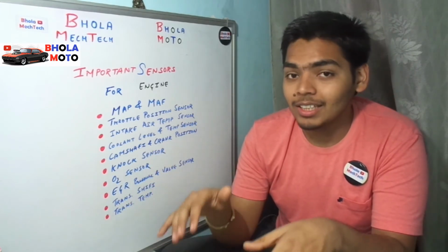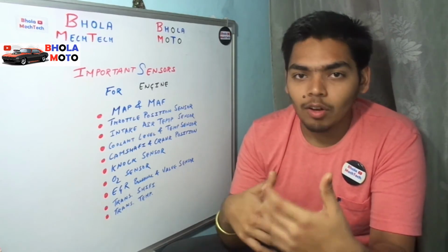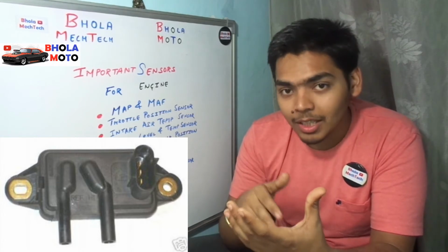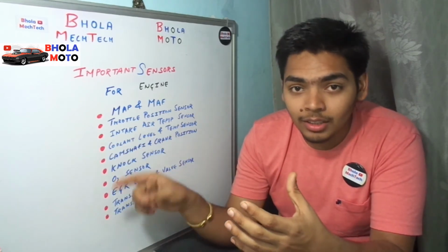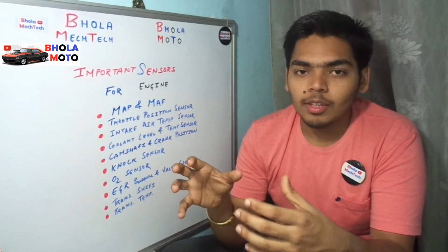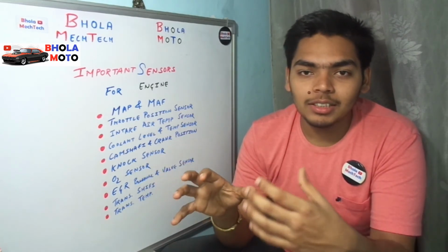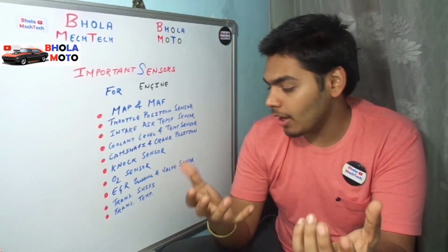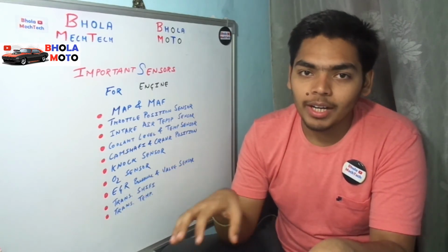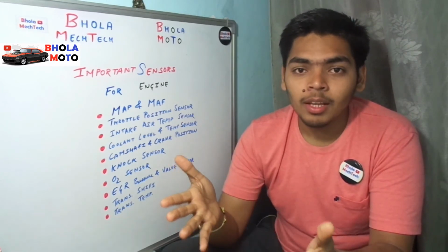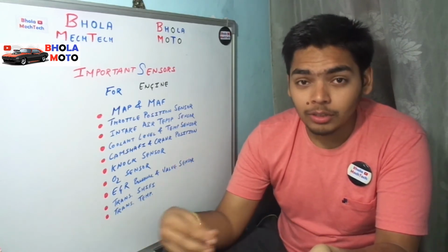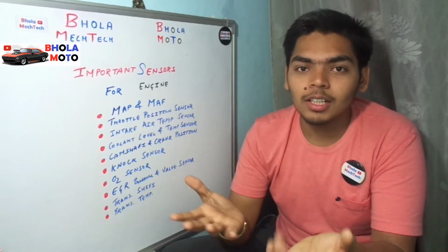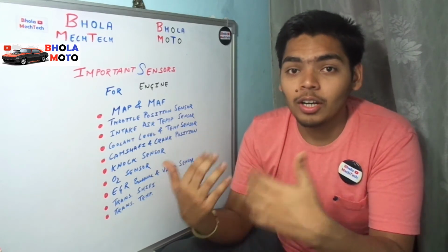Now coming to another point, that is the EGR pressure sensor and EGR valve sensor. EGR is the exhaust gas recirculation, and the EGR pressure sensor senses the pressure in the whole system of this EGR. So if the pressure in the EGR system reaches above a certain level, then there are chances of some dangerous things to happen. So that's why EGR pressure sensing is also required, and if the pressure is quite low in the EGR system, then it is quite difficult for the exhaust gases to re-enter. Another thing is the valve sensor, which is required to turn this system on and off.